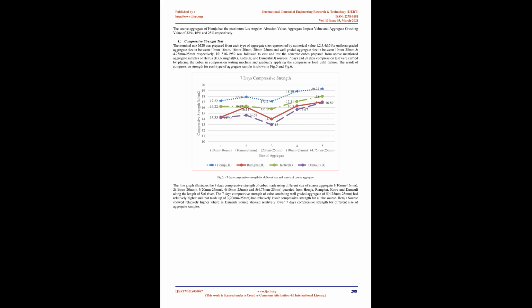After 24 hours these molds were removed and the test specimens were put in water for curing until 1 day before testing. The top surface of these specimens was made even and smooth by using cement paste, spreading it smoothly on the whole area of the specimen. These specimens were tested by compression testing machine after 7 and 28 days. Load was applied gradually at the rate of 140 kg/cm2 per minute till the specimens failed. Load at failure divided by area of specimen gave the compressive strength of concrete.